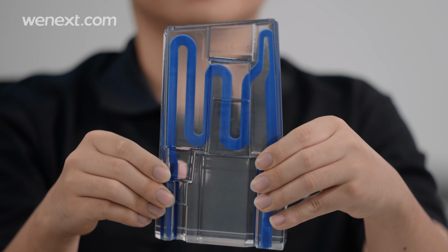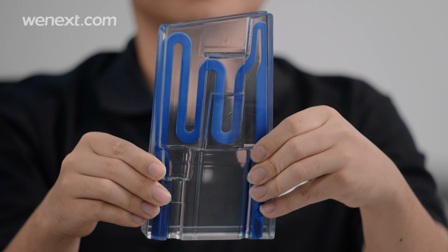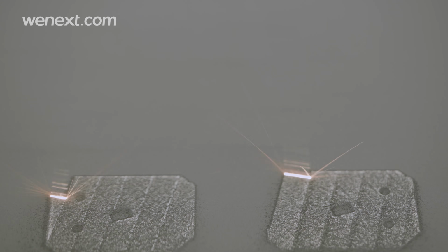CNC, especially 5-axis, is capable of producing parts with extremely high dimensional complexity. However, due to the subtractive nature of CNC, there are some products that CNC cannot produce, such as conformal cooling channels and cylinders, curved pipes. So our recommendation is SLM metal 3D printing.